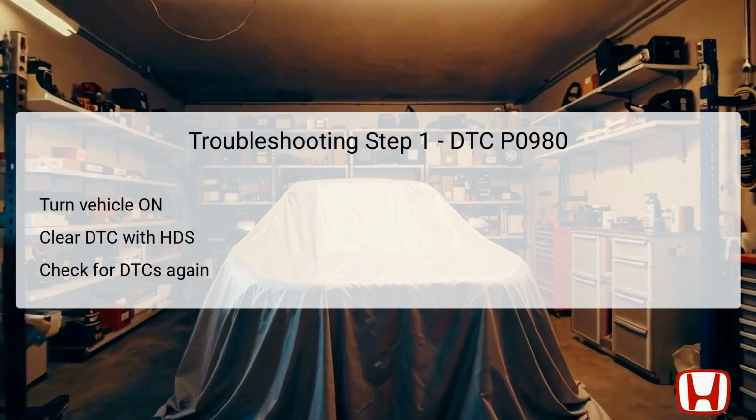The first step in troubleshooting DTC P0980 is to turn the vehicle's ignition to the on mode while ensuring all electrical systems are operational. After powering the vehicle, the technician should use the HDS Honda Diagnostic System to clear the DTC. Clearing the code is essential to reset the PCM's memory for subsequent checks. Once cleared, the engine should be started with the brake pedal firmly pressed, shifting to either neutral, N, or drive for at least 1 second.